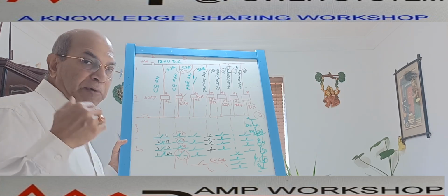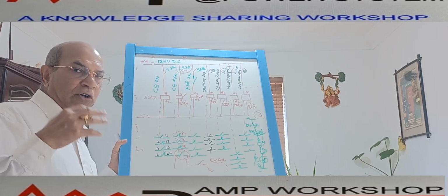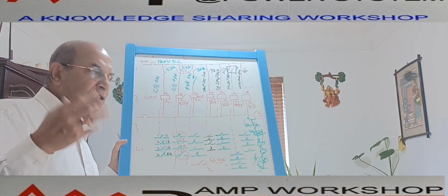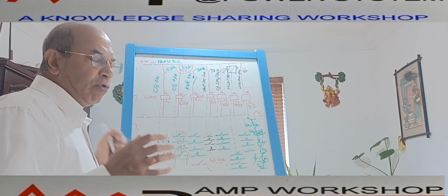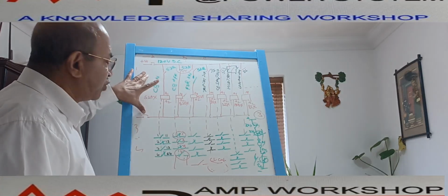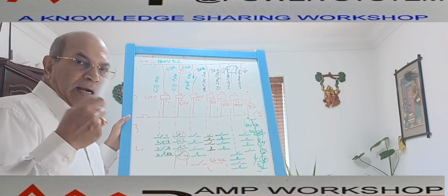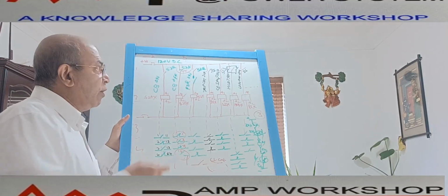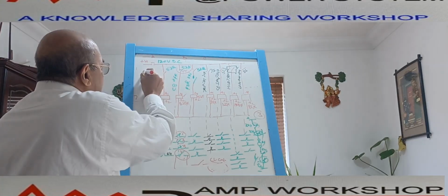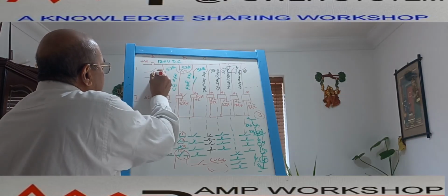Then we use it for the circuit breaker spring charged or not charged condition. To sense that condition in multiple locations, we use the auxiliary relay. Similarly, we have seen that each circuit has an MCB. If this MCB is tripped, we need to know. So we need at least one alarm that the MCB has tripped. For that reason, the MCB auxiliary contact, I have already told you that an MCB has at least one NO and one NC contact.